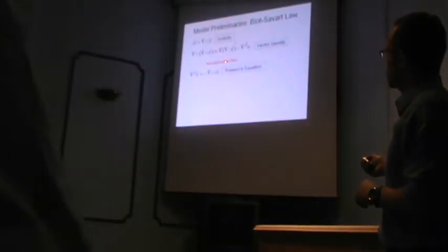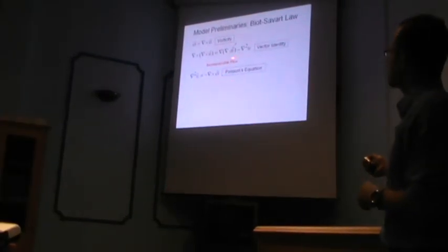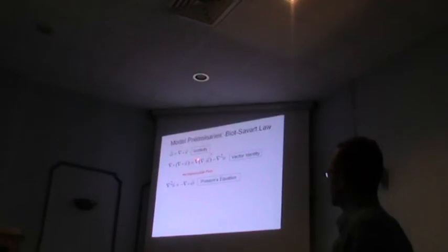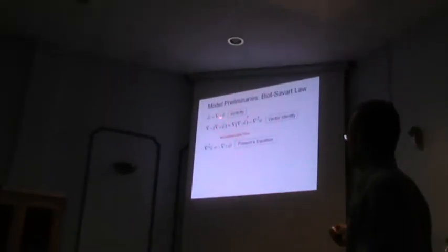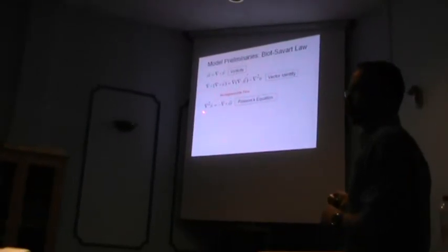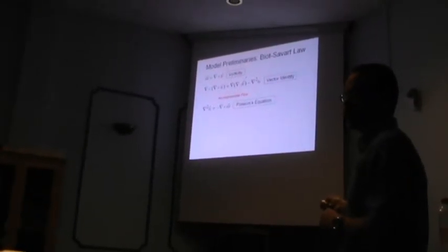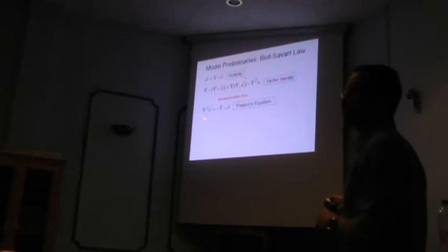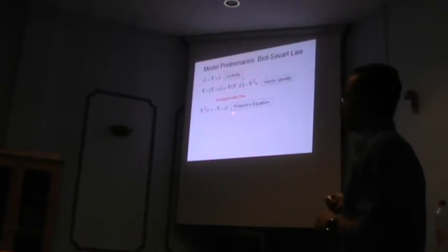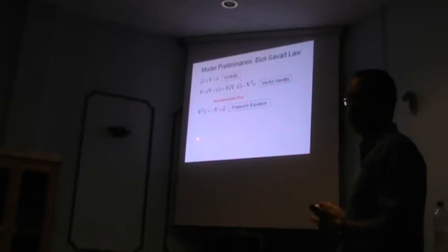And we capitalize on the fact that this is incompressible flow. And because this is incompressible flow, the divergence of the velocity field is 0, and we can basically plug in that del cross u equals omega from here, and we get this particular equation. So this particular equation, you can think of it as an equation in the unknown field u, given a known field omega, and this is a very well-known equation, which is Poisson's equation.